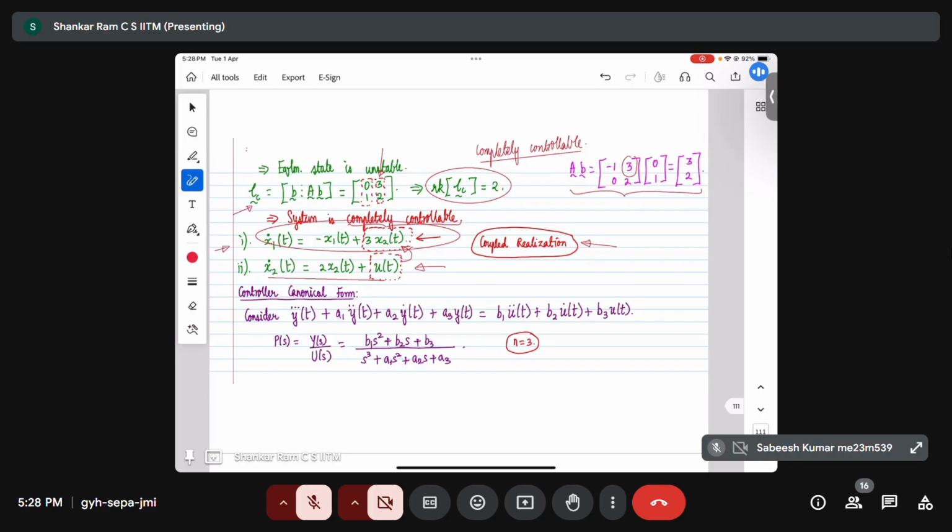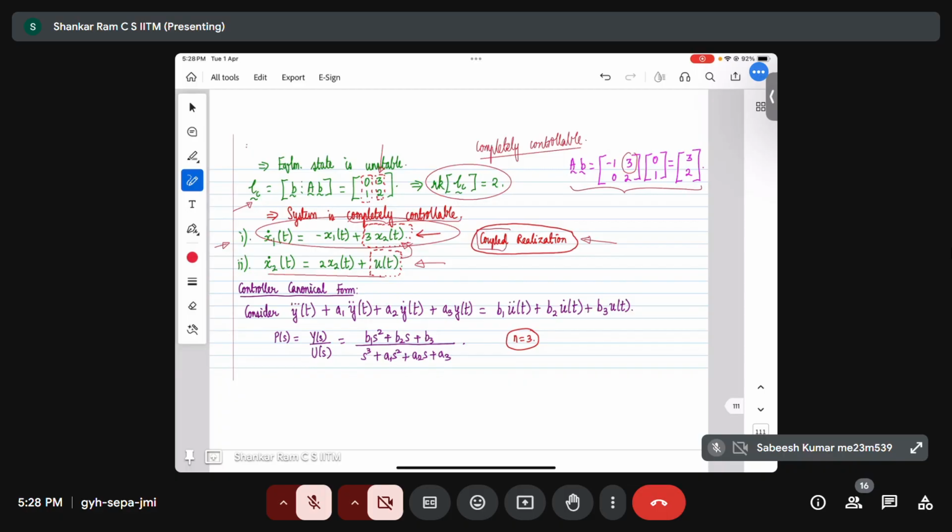So in this particular case, the way you and I have used the adjective coupled in this discussion, I'm drawing a boundary for our discussion today. When we call a state space relationship coupled, what you and I are saying is that the evolution of a state variable is not only dependent on itself, but also on other state variables. That's what we can observe here, right? If you look at the evolution of x1, which is x1 dot, it is dependent on x1, but it is also dependent on x2. That is why it is a coupled relationship. I hope that provides clarity, right? Thanks, sir.